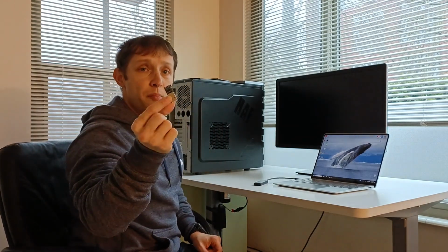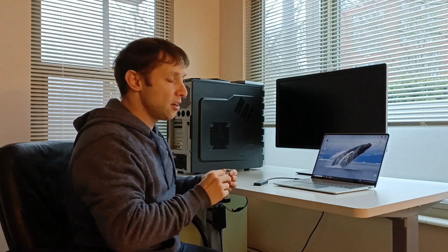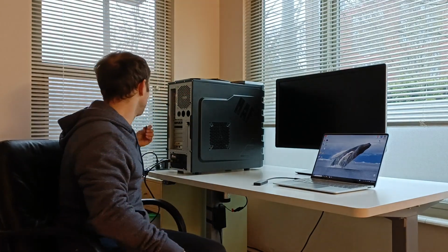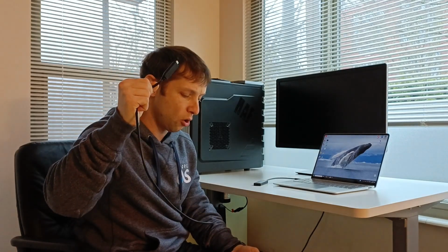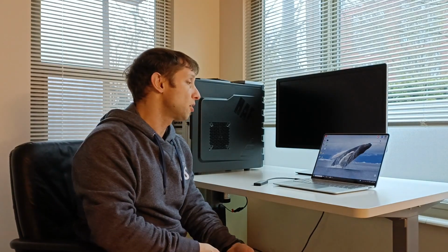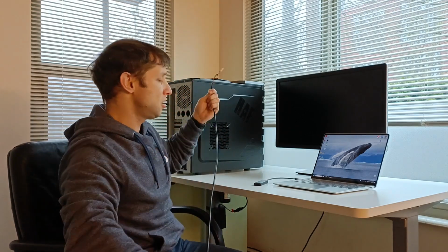You can buy it easily for only $1, but then you need to buy an USB to serial converter, which allows you to create a cable like this one, where you can see on one side there is the USB-C port that needs to be connected to the host. When I talk about the host, it's the computer or system that you are using for controlling all the others. In this case, this laptop for this example. And on the other side, after you do some soldering work, you can have this port. This port is the CH9329 controller connected to the serial interface.